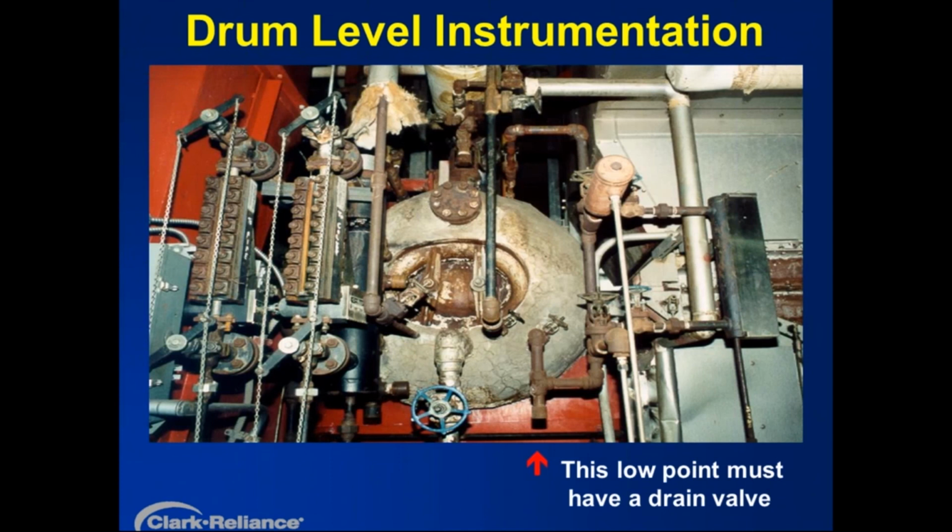This is a slide of a typical package boiler, and what we're looking at on the left are two gauge glasses attached to a water column. You can't see the levels in those gauge glasses due to the angle of this photo, but assure me they were operating correctly. And you can see chains connecting those valves together that are properly installed. And there's drain piping coming off of those lower water gauge valves right alongside those chains. Going back to the water column behind the right-hand gauge glass, there is drain piping coming off of it, and actually everything's pretty good on that side of the drum.